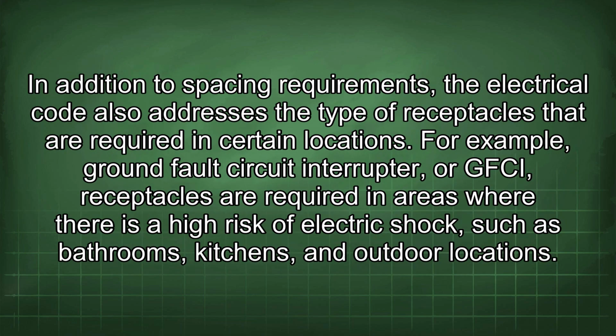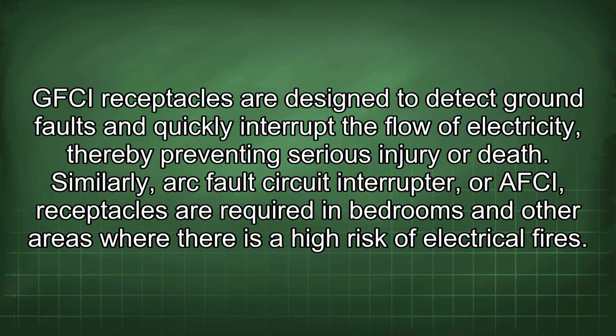In addition to spacing requirements, the electrical code also addresses the type of receptacles that are required in certain locations. For example, ground fault circuit interrupter, or GFCI, receptacles are required in areas where there is a high risk of electric shock, such as bathrooms, kitchens, and outdoor locations. GFCI receptacles are designed to detect ground faults and quickly interrupt the flow of electricity, thereby preventing serious injury or